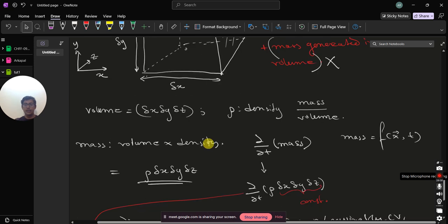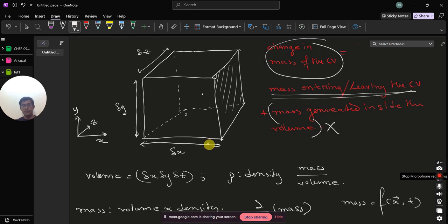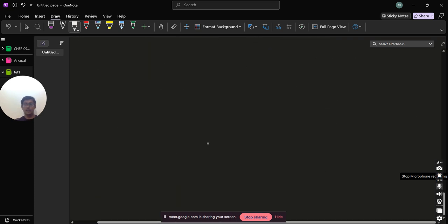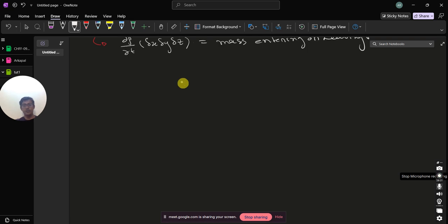So, for example, we have the values at the center of the control volume. Let me just do a 1D demonstration that will be helpful. So, for example, this is the midpoint of the control volume, and we know the rho here. We know the velocity here, u, v, and w. But what will be the flux here? So for example, let this phase be the east phase. Okay. So what is the flux?